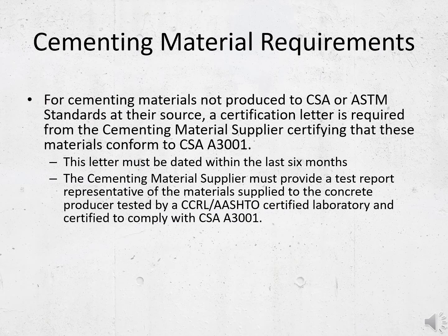As mentioned earlier, the auditor should be looking for current documentation indicating that the cementing materials used comply with CSA and that they've been tested by a lab certified to CCRL or AASHTO.